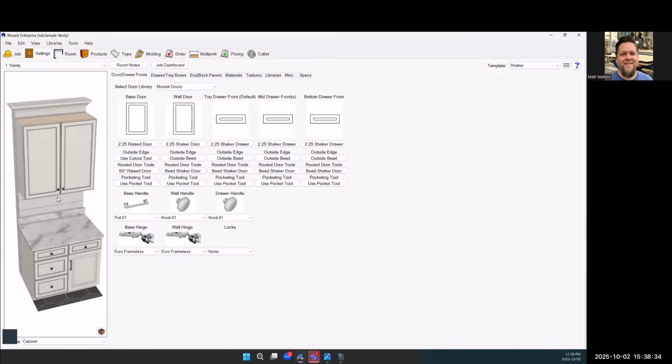those. If you're looking at pocketing tools, I would recommend going to like a diamond finish over an insert, but the inserts work great as well if you're not doing high volume doors. But if you're doing a ton of doors every year, it's going to pay for itself using those diamond coated bits.